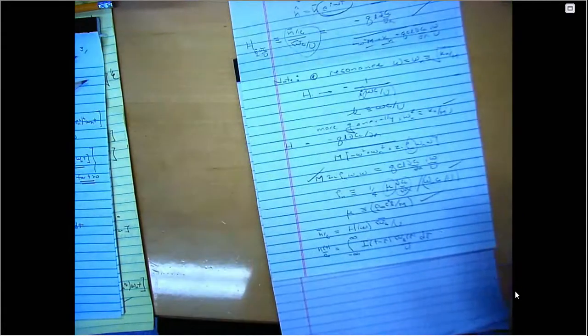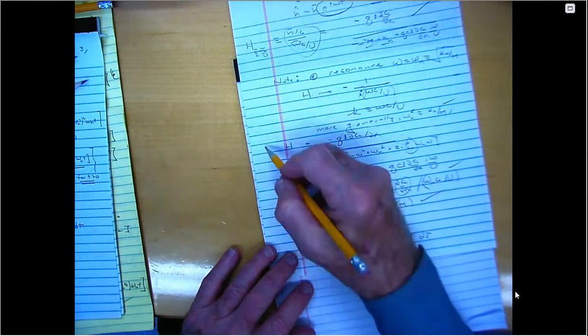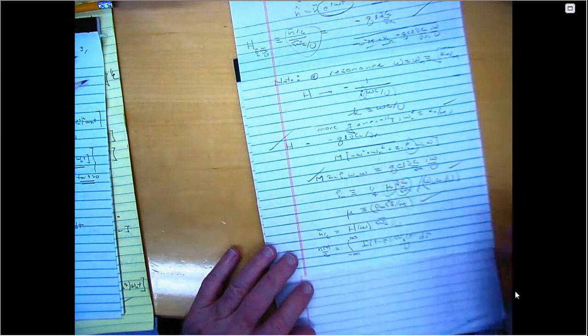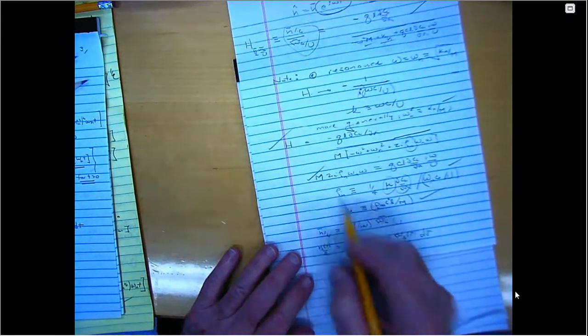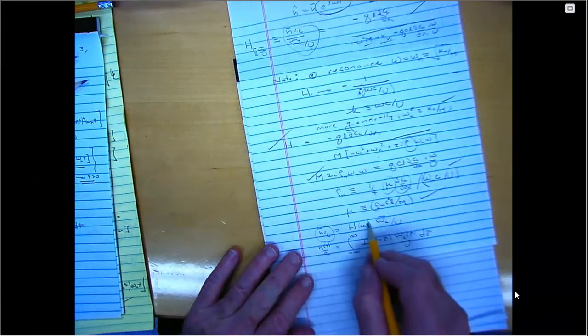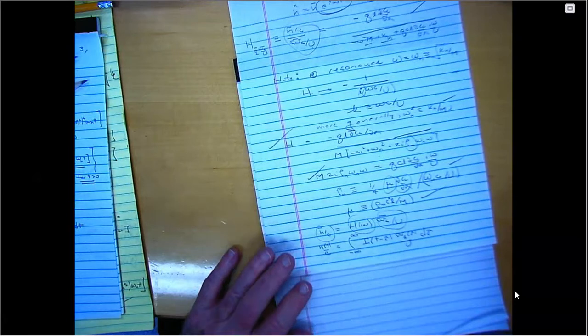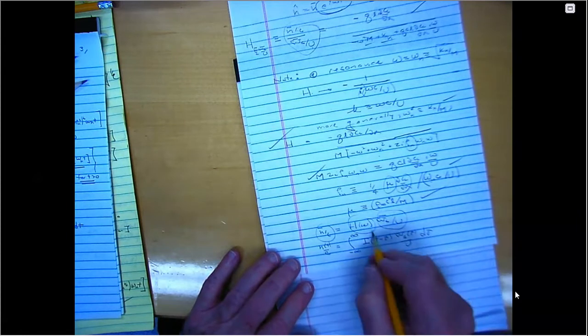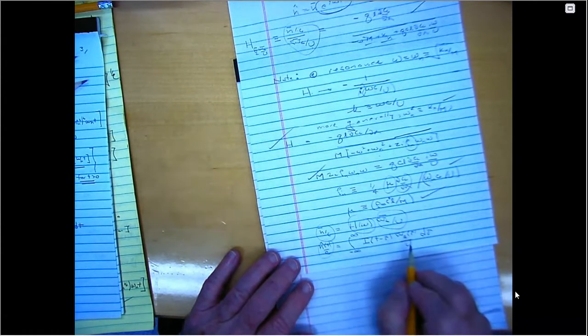Okay. So with all that, we can write this transfer function in this form, which is a nice form for subsequent use. And having defined this transfer function, we can also say that the amplitude response formula is the transfer function times the amplitude of the gust. And if I believe in Fourier transforms, I can inverse Fourier transform this expression and find out how h hat depends on time.